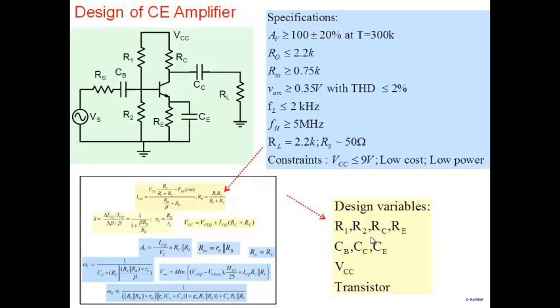All right. Also, you have to be aware of what transistors are available. You also have to be aware of all the values of resistors that are available. You know that a resistor of 2.2 may be available as a single resistor, but 2.3 is not available. As a single resistor, you'll have to connect 2.2 plus something, and that makes the circuit a little bit bigger here. All right, so this is what you have to do.